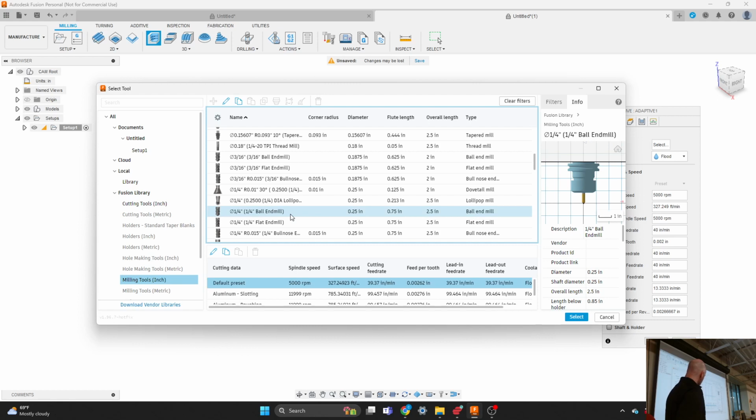You don't have to do this with the ball end mill, but we're definitely going to do our finishing pass with the ball end mill. And it'll save us a tool change if we just use our ball end mill for the roughing pass as well. And it's kind of height or size based, so it kind of starts at small on the top. Cool.